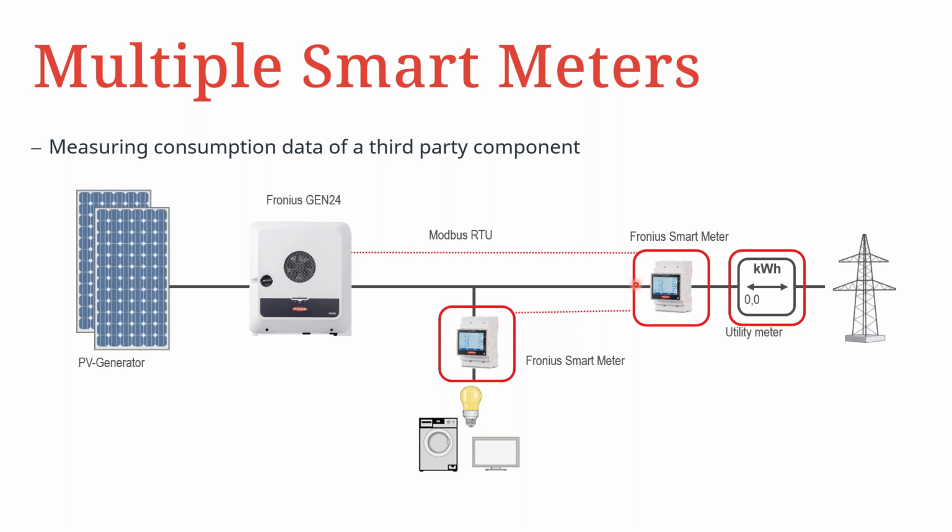The consumption path basically means that inverter power will be connected to the grid side of the smart meter, and therefore this will be the description or the positioning of a smart meter along the consumption path. So you could have a maximum in this case of about 4 smart meters. You have 1 primary smart meter and the possibility to have an additional 3 secondary smart meters.